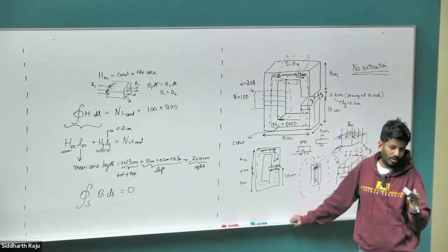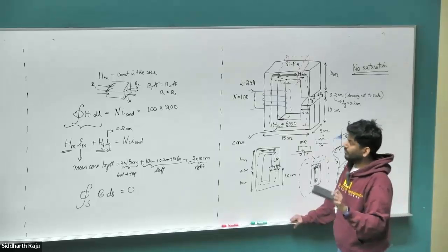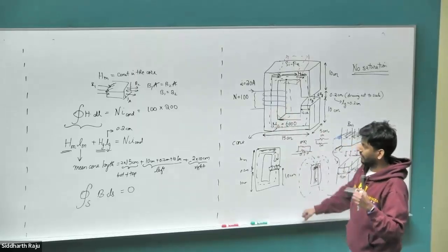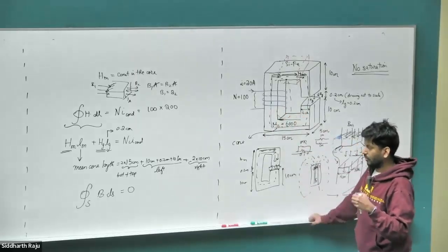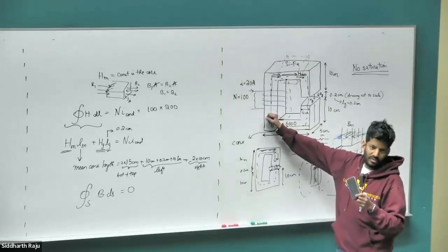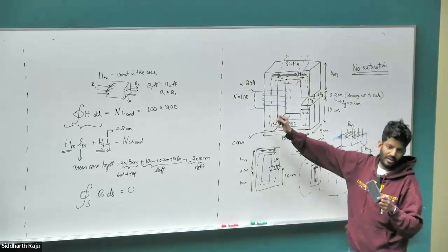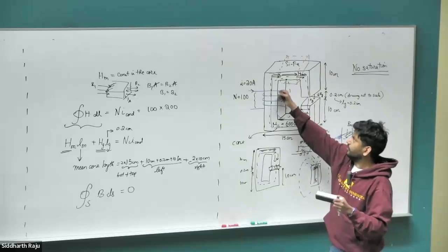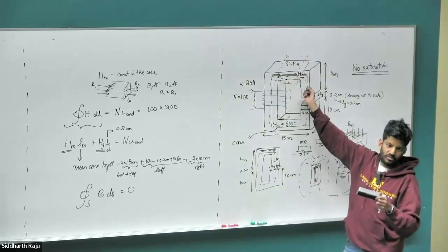So it is not as good as a copper wire. Right? The copper wire is a way better conductor compared to the magnetic conductivity of the iron core that we have. And the second bigger problem would be once this core starts to saturate, the core will start to behave like an air gap. Right? At that point, all the field lines will start to leak through multiple different pathways. It will no longer have a preference to stick through just the iron core.